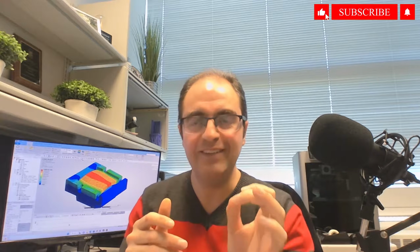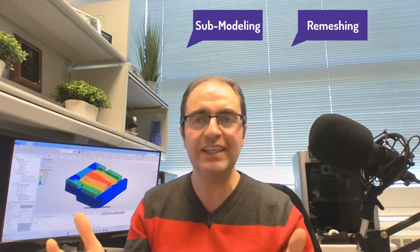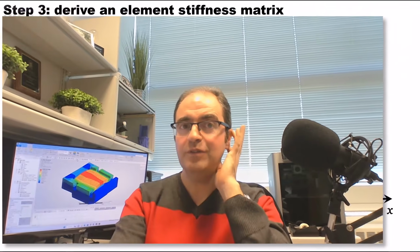In fact, this is the formula that creates those colorful contour plots in finite element that we like to put in our report. This equation is extremely simple and extremely powerful. So I want you to really appreciate how important this formula is, and that's why I'm spending more time on this. You can also do many more advanced stuff in finite element. For example, if you want to do submodeling, if you want to do remeshing, these all come from this very important formula. So don't forget that u equal to N A. Let's go to the next step.